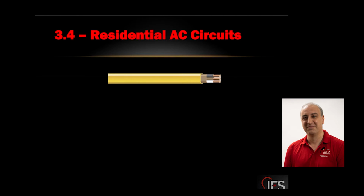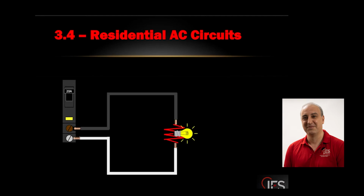Now, I'm not going to show the equipment grounding conductor, the bare or green copper, anymore, because that is only a safety line when something goes wrong. So under normal condition, this is your electric circuit. The source of power in our AC system is usually the service, right? Service comes to our panel, and each breaker becomes the source for that specific circuit. So here we got a 20 amp breaker connected using the two wires to the light bulb.